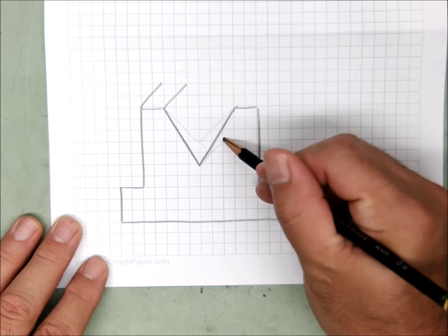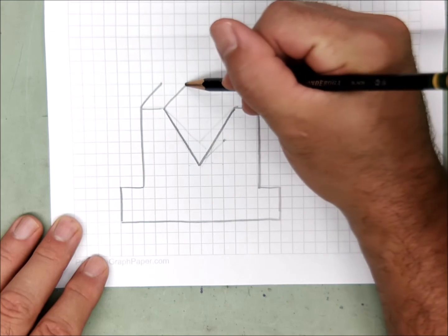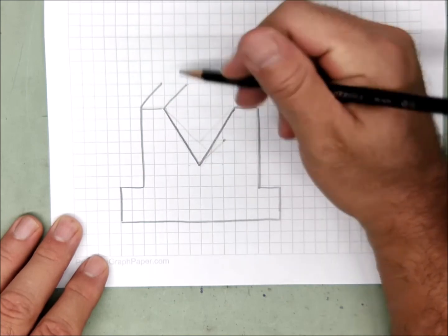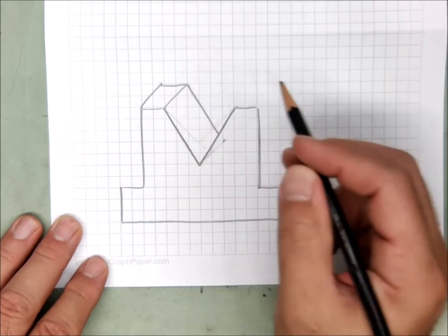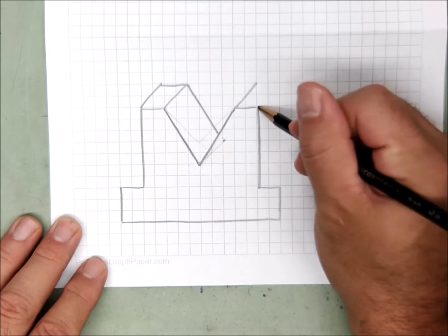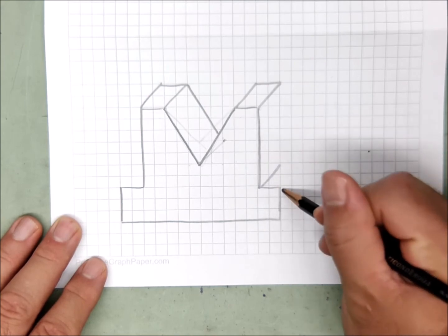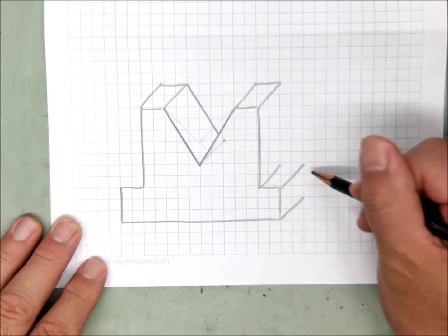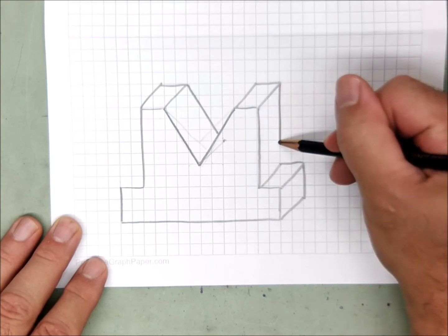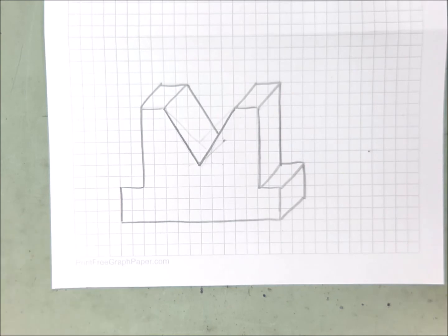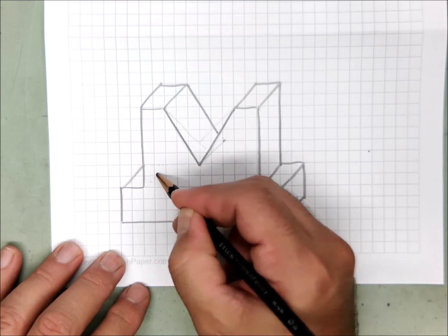I can't see the very bottom of the valley here, the vertex. But I want to know where it is, because I'm going to have to connect that point to here, just like this point connects to here. And this gets connected, and then 1, 2, 1, 2, these get connected, 1, 2, 1, 2, 1, 2, and these will get connected. Vertical in the front gives you vertical in the back, and then 1, 2, so we know that there is a surface out here.